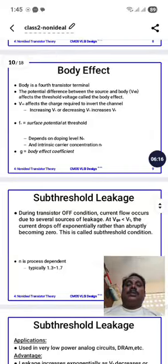The potential difference between the source and the body affects the threshold voltage, called the body effect. Whenever a potential difference is applied between the source and the body, it affects the threshold voltage. For example, the transistor becomes active at a particular voltage, 0.7 volts for silicon and 0.4 volts for germanium. This is called the threshold voltage. But an increase in the potential difference between the source and the body, that is VSB, will affect the threshold voltage, so the entire substrate is affected. This is called the body effect. VSB affects the charge required to invert the channel, and increasing it increases the threshold voltage.